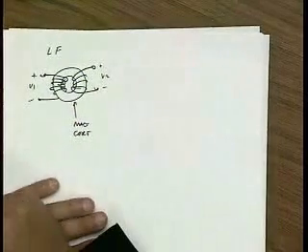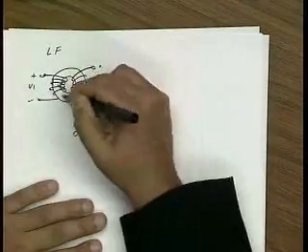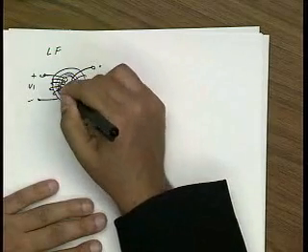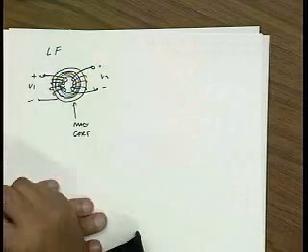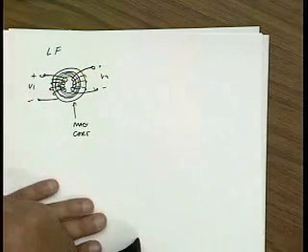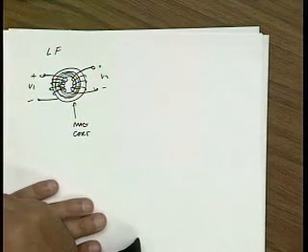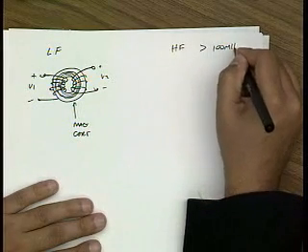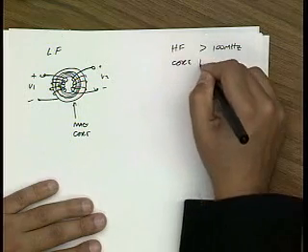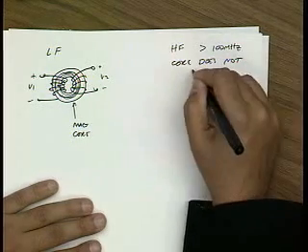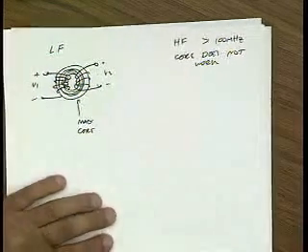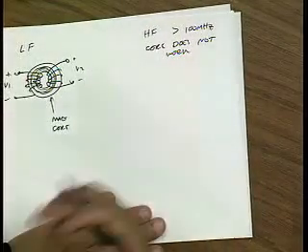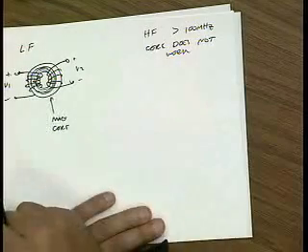Now at low frequencies, this core is very nice because all the magnetic flux from this winding goes inside this core and reaches V2. Okay? Unfortunately, at high frequencies, let's say above 100 megahertz, the core doesn't work. Okay? So it's very hard to find magnetic materials that work at high frequencies. So at high frequencies, this core is essentially not there.